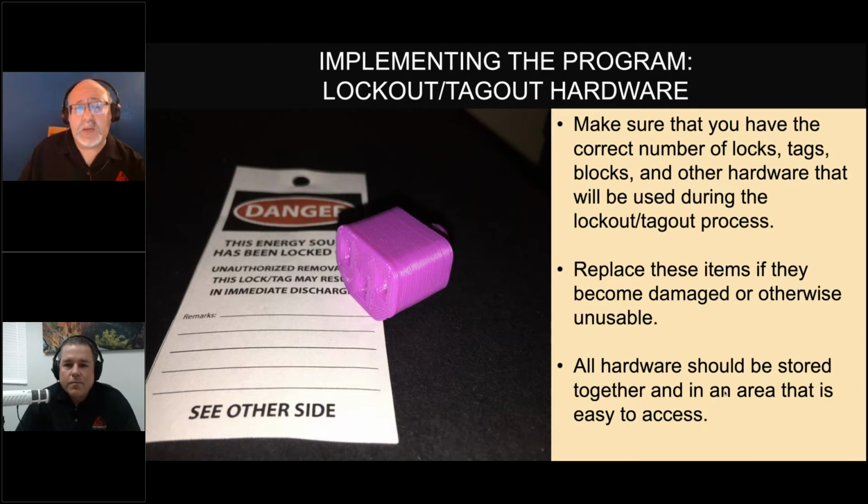Sam, in your inspections, have you seen lockout tagout stations, and what's usually wrong with these things? A lot of times when you go out and look at lockout tagout stations, you'll find just Master locks and they all have the same keys. That's a bad deal.